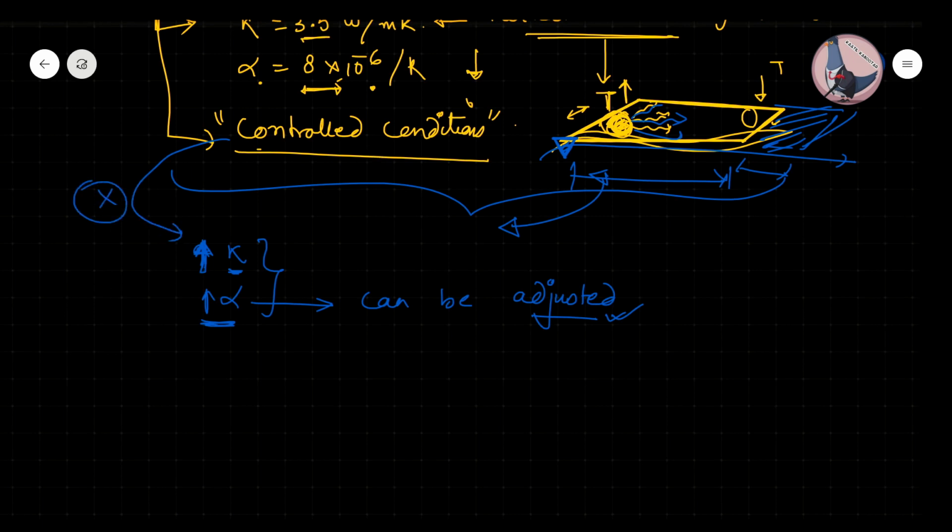So a very good option nowadays that we are trying to explore is aluminum. Now it is a very surprising choice. Many times in interviews, people ask whether aluminum can be used as machine structures. People will first say no because of this alpha value, that the deformations will be very high. But you should also know that this can be adjusted. So nowadays aluminum is also used.